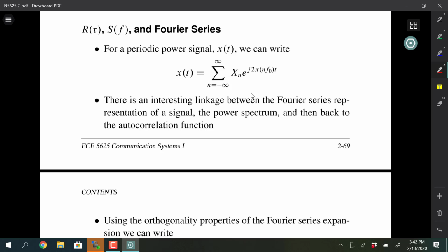And it'll show other nuances, like if there were multiple reflections, as in multipath, you'll see a strong correlation peak, and then you'll see next to it some weaker peaks, which will be the signal that bounced off of other things further away. So like echoes or reverberations, and that makes sense, right? You surely understand that from sonar. You'd get a blip back, but you can correlate the local signal against the received collection of waveforms, and then you can get a stronger indication.